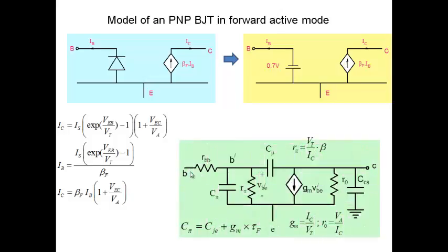The small signal model is exactly the same. Same RBB, C pi, C mu, everything is the same. Same equations, everything is the same. No difference between the small signal model of an NPN and a PNP. If it's bothering you why this is still down and these are going up, we can have a separate discussion some other time on that. It will require a little bit more discussion. But the point is the same model. Same model for PNP.